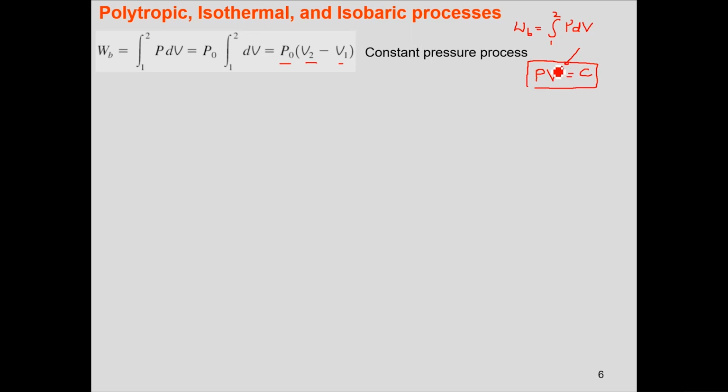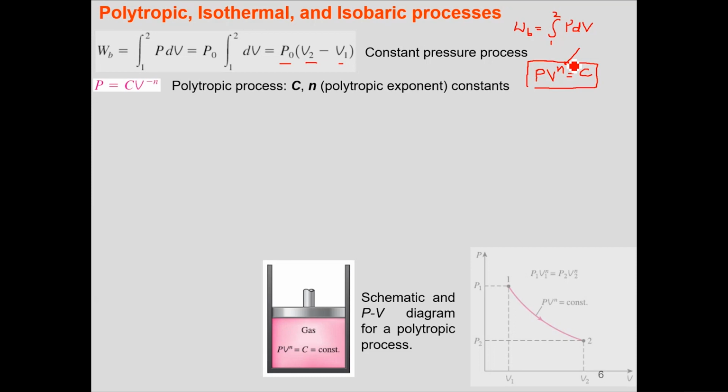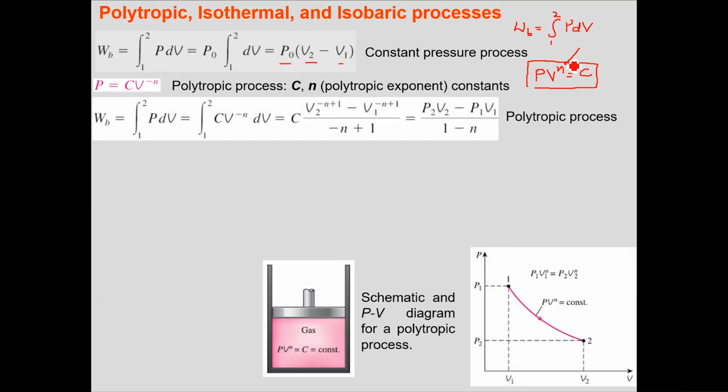If the fluid within a system is following a polytropic process, we know that the boundary work could be associated with this expression, where we have seen the integration of this expression, and we know that the polytropic process follows this amount of boundary work, P2 V2 minus P1 V1, and n basically represents the path through which the work done can be calculated.